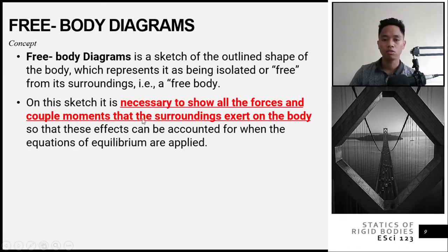Pero take note that you should also show all the forces and couple moments that surrounding exert on the body. So whatever forces or moments, external moments and forces acting on the body, you should always include that in your sketch. Okay, although imo siya free, okay, gitangtangan nimo siya mga supports, naka-isolate ang imuhang member. Pero again, you need to show all the forces and the couple moments acting on the body. Okay, so that these effects can be accounted for when the equations of equilibrium are applied. Again, you will know that later if we have some examples.